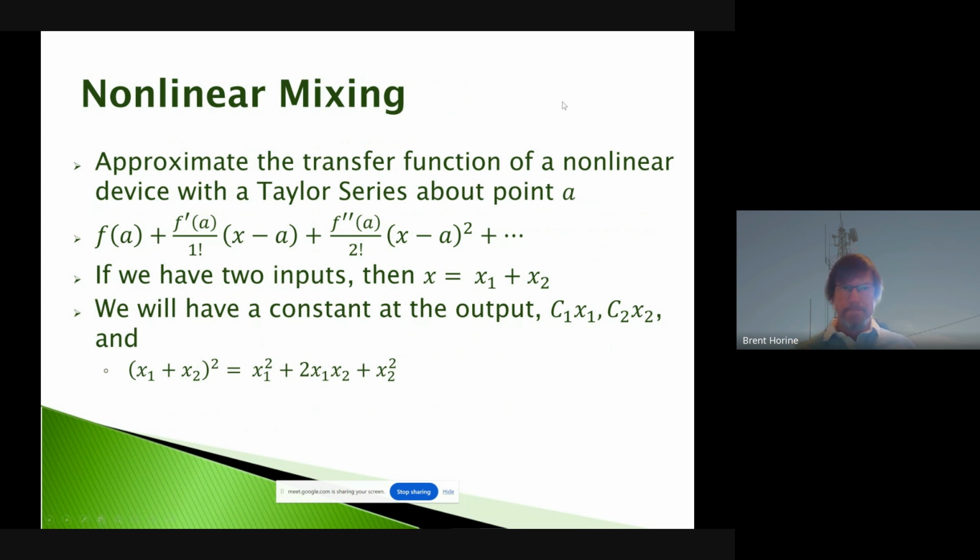If we multiply two signals, and one signal is a higher frequency cosine, giving you impulses in the frequency domain, then we are translating that spectrum to the frequency where that impulse is, where that cosine is at, right? So that's kind of what we're doing here. We're doing some multiplication, right?